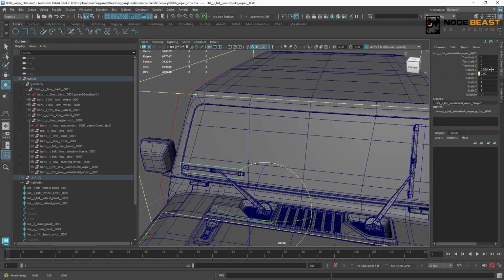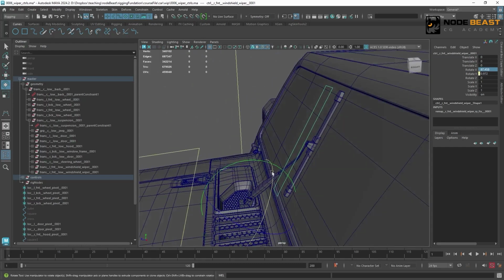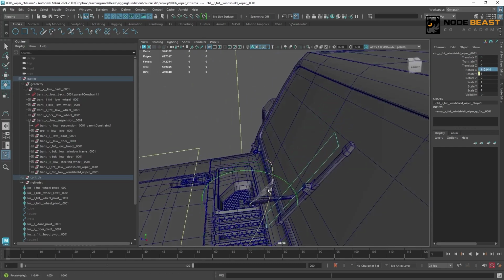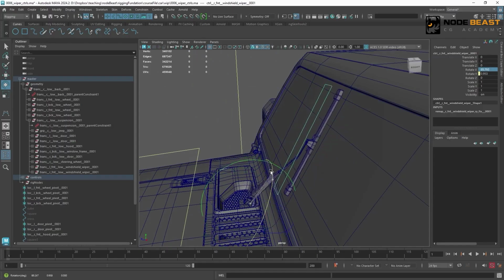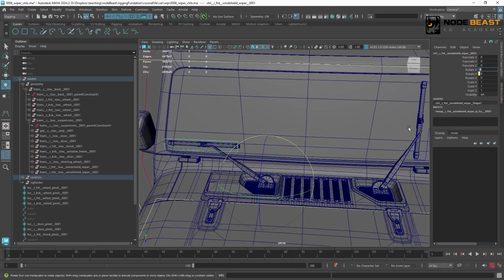When we go back to 0 degrees, the y-axis has no value. But as we continue to rotate towards 90 degrees, the y-axis will produce a value. When we rotate past 90 degrees, it remains 1. This 1 degree will help us solve the intersection problem. The main thing we used here was changing the rotate order to make the y-axis follow the x-axis's changes to achieve this effect. Let's zero out the controller.